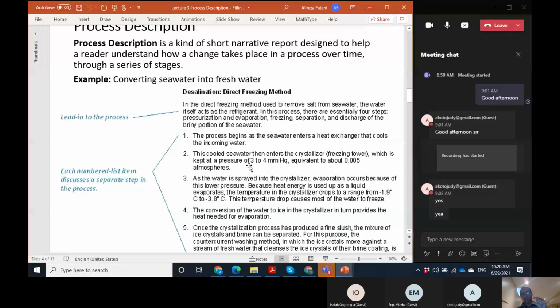Or which type of sensor is available. These are important. Whether we have a pressure switch to measure that the pressure is less than 3 or more than 4, or we have an analog sensor that gives us the pressure in any value. So these are things that we should check, and according to that, prepare the program.